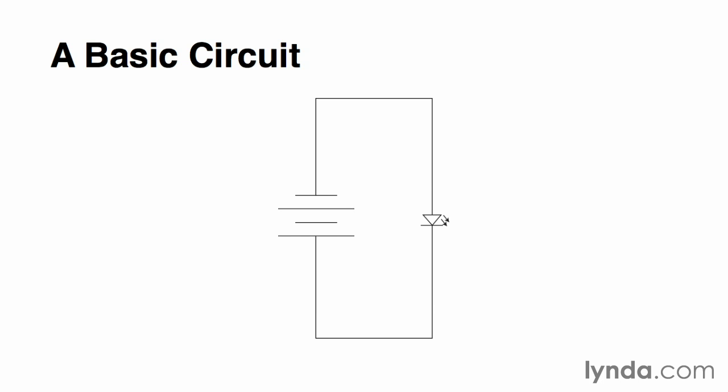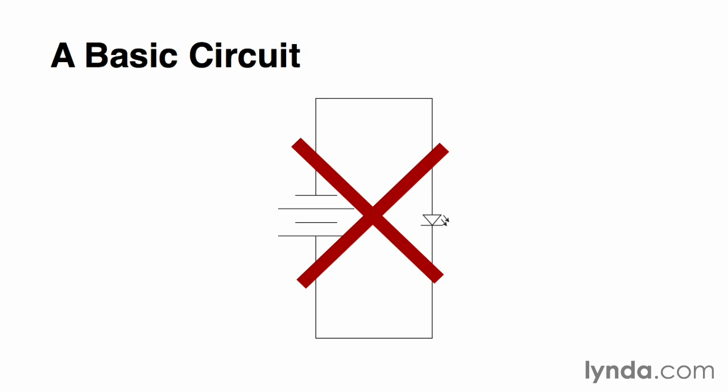Well, when dealing with circuits, the big no-no is connecting the positive directly to the negative side of a power supply, such as using the 5-volt output pin from the Arduino, connecting it to an LED, and then right back to ground. This is a great way to break a lot of LEDs in a hurry, and I speak from experience. This is referred to as a short circuit.